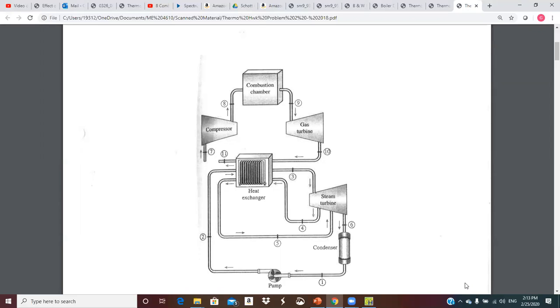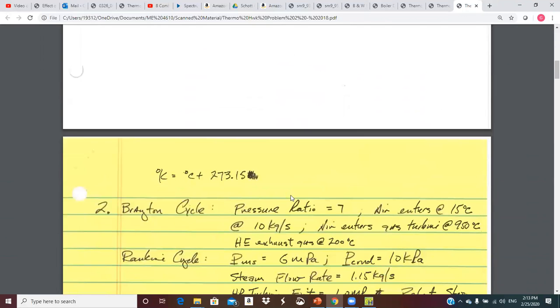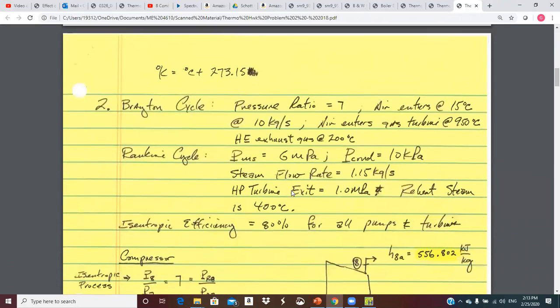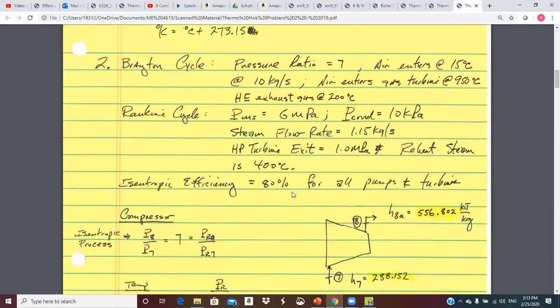And we've got this, our heat exchanger is our boiler, and so we're generating main steam, and then we're doing some reheat after a partial expansion back into the turbine, and then we come out to a condenser and a pump. So this is a little bit of a strange device here. So we'll look at it. Well, so there's some of the details on it.